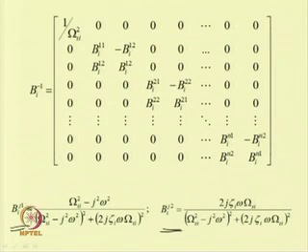So, in this way, one can use this harmonic balance method in these three cases, that is the modal reduction method, dynamic substructuring method or component mode synthesis method, to reduce these equations to a set of algebraic equations, and those equations have to be solved to obtain the response of the system.